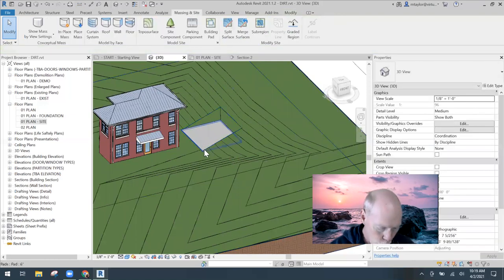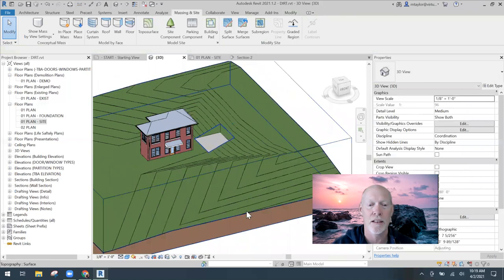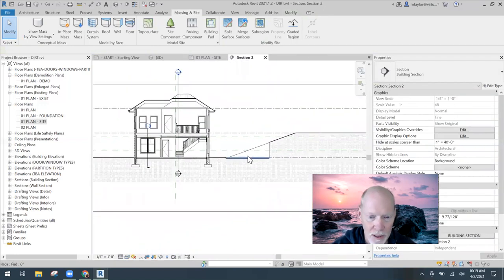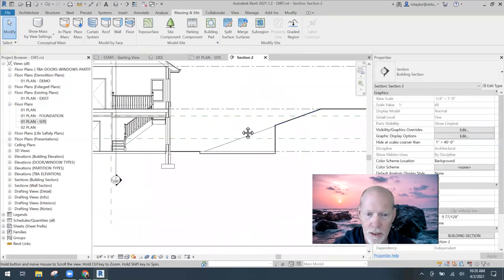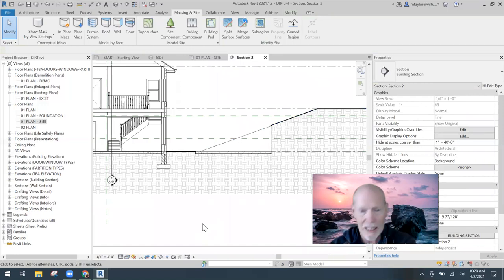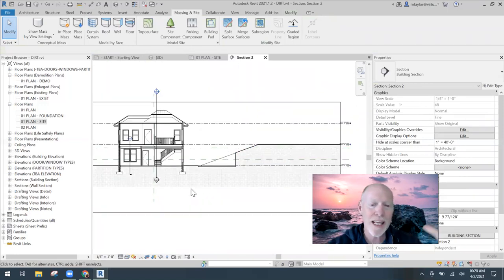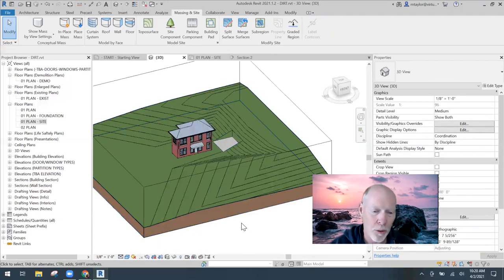So there. You could now walk out of the building and walk over onto that pad, and it has cut out the hill, okay? And you can see that in my section. See, there's my 6-inch. It has cut out the hill. It displaces soil. So I just wanted to show you guys how to get dirt under your building in 2D and 3D. So I hope that helps.